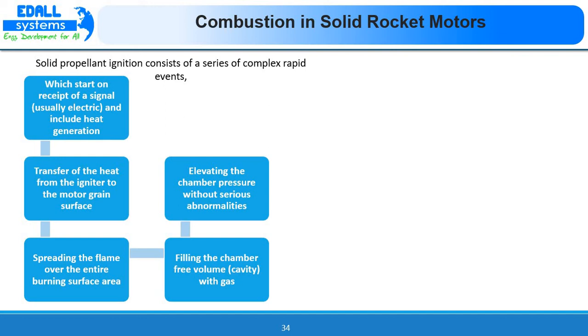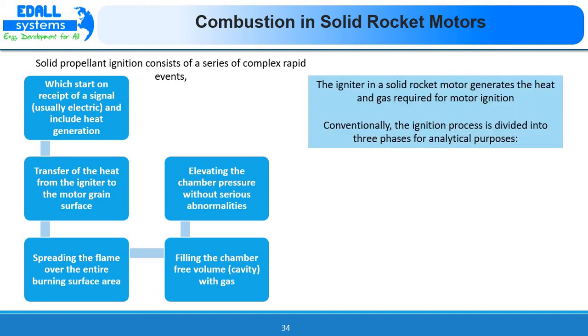So these are the rapid events which happen inside the combustion chamber when the igniter is ignited and the combustion initiates. The energy released in a combustion is between 95 and 99.5% of the possible maximum, and this is difficult to improve. The rocket motor designers have been concerned not so much with the burning process as with controlling the combustion, because it involves start, stop, heat effects, and various other parameters, and with preventing the occurrence of combustion instabilities also.